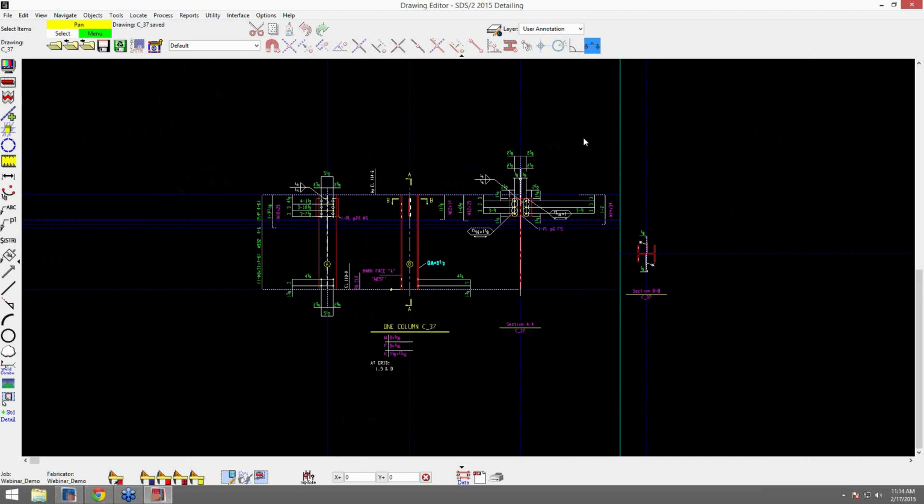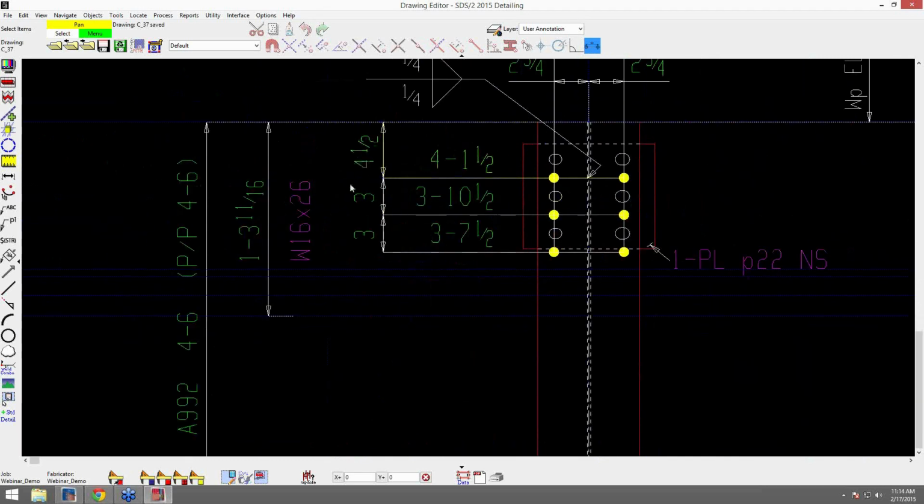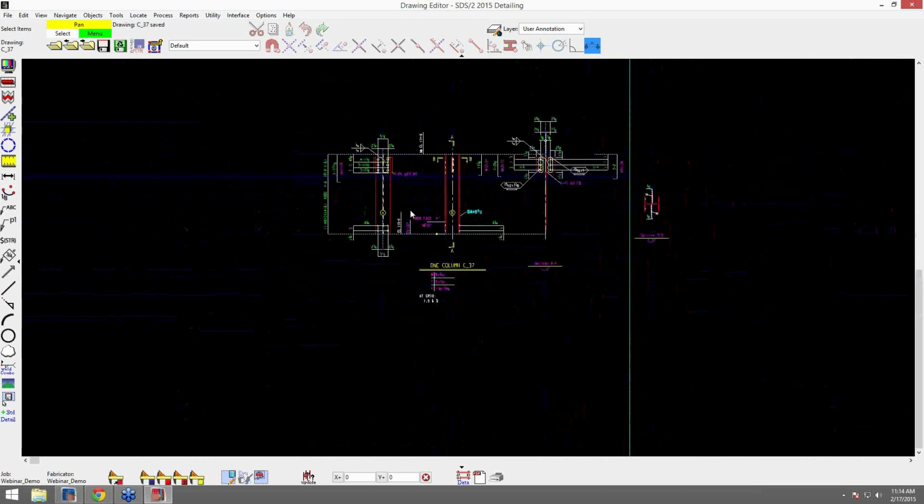So in the end here this morning, we've talked about a few different things. We've talked about really what are templates and where are they going to be stored at, how they're applied just by scouring through the member detail, looking for all the named locations. Once they're matched, it applies the particular annotation or particular dimensions. We've also shown some different tools to list or to visually see the different named locations and their properties.